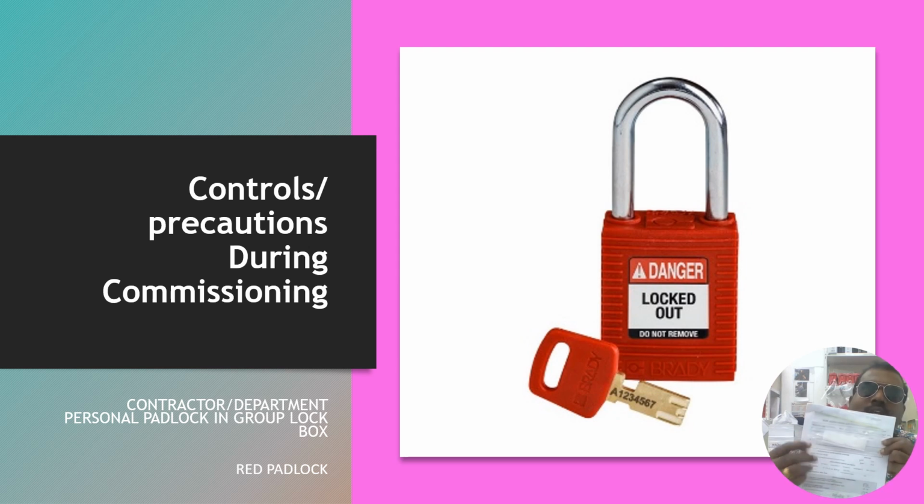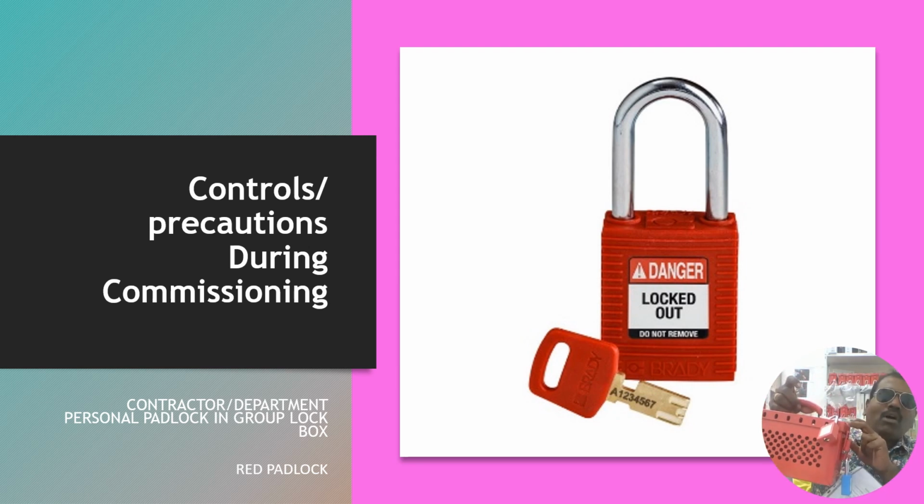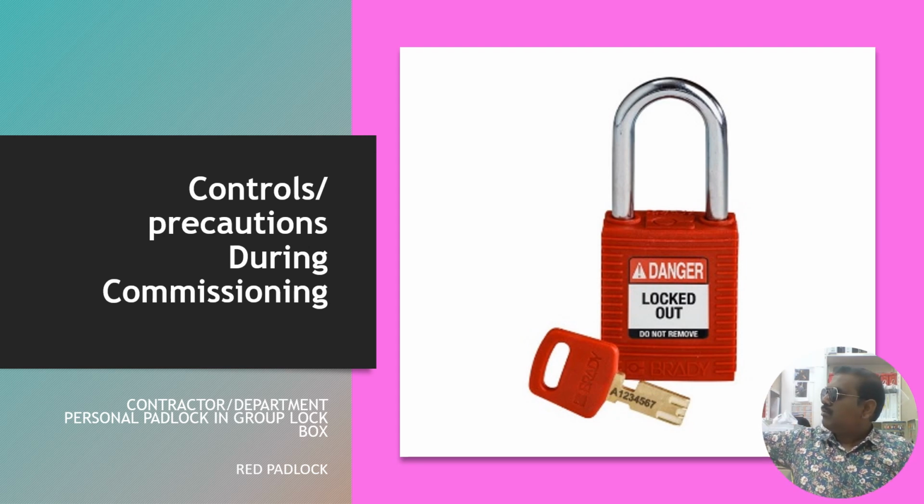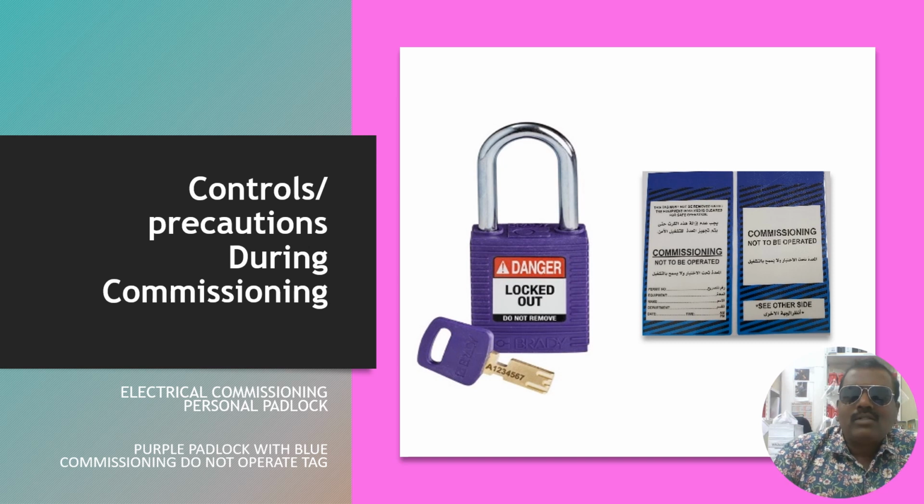At this time, we will remove this key and the LOTO department key from this box. So we can open this box, take the key outside, go to the site, remove the isolation, and restore the system for operational activity. So what is this purple one?